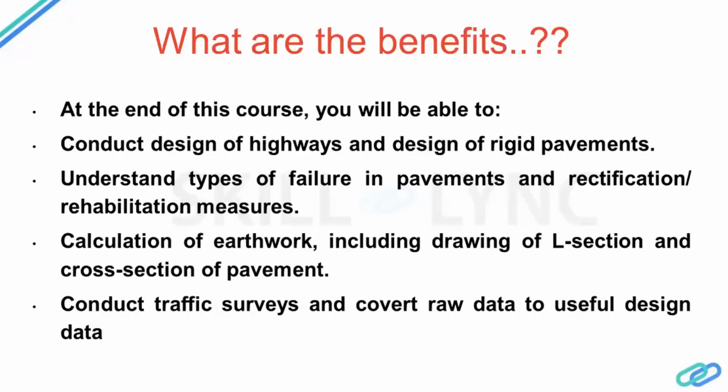Then we come on to the traffic surveys. This is one of the basic inputs that tell you how to design a highway. I can design any pavement that can withstand a load of, say, a rocket ship. But when it's not going to serve that purpose, when I only need, say, 10 trucks to travel on that road, why should I design for such a heavy load?